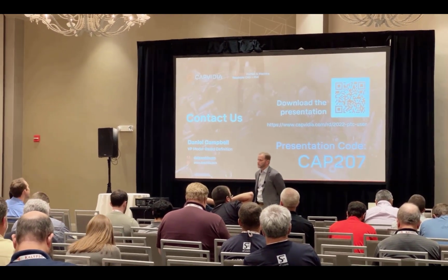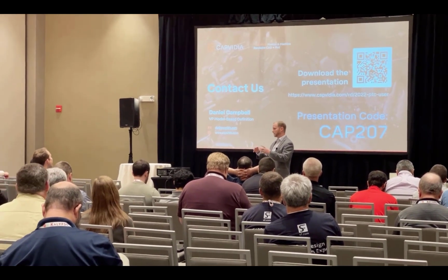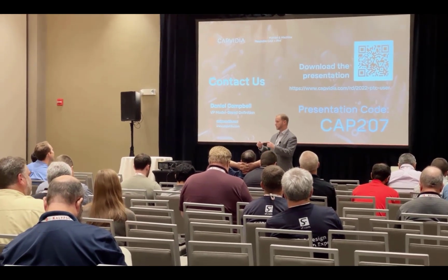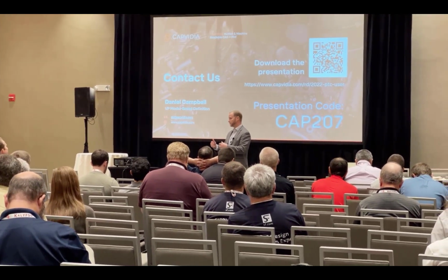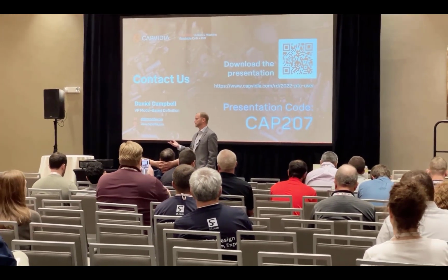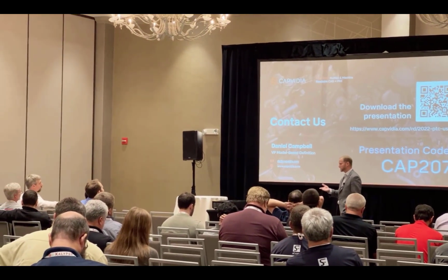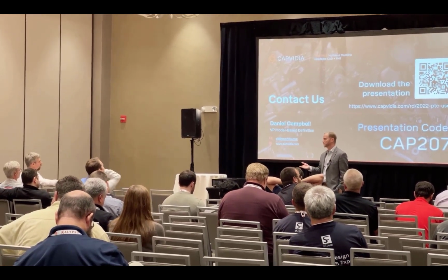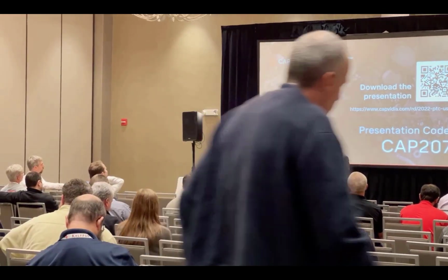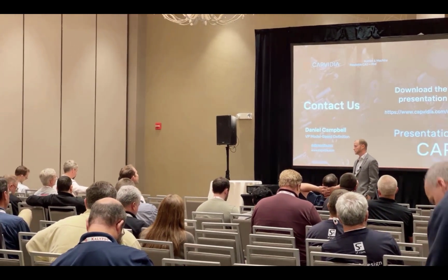And the way QIF is designed, you could ignore a lot of the complexity of the product model, like all the CAD geometry, and just look at what's called the features and characteristics. You could pick apart that data, look at real results, and create your own analytics. Because ultimately, there are standard analytics that every company is going to want to do, but every company is also going to have their own analytics. That's a really important part of QIF: it makes it super accessible for companies to be able to do that.